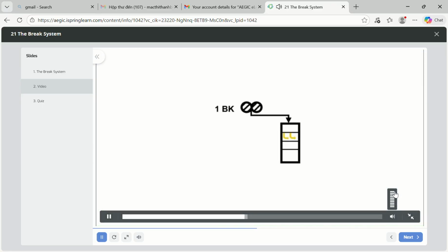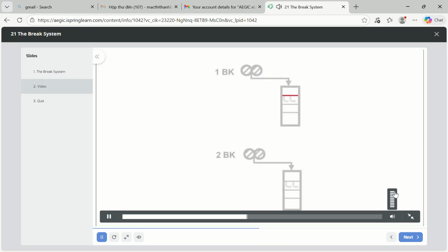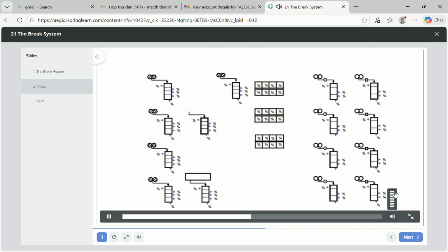Balancing the mill begins with achieving the correct release for first brake. Once the first brake release target has been achieved, the split between the stock tailing the screen and the stock passing through the screen in the first brake sifter section can be considered to be optimized. This is the first step towards ensuring the stocks are distributing through the mill in the proportions that the mill has been designed for.